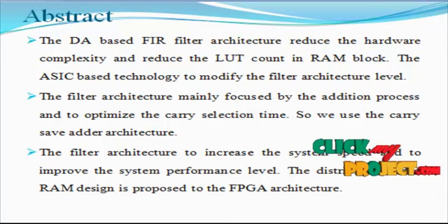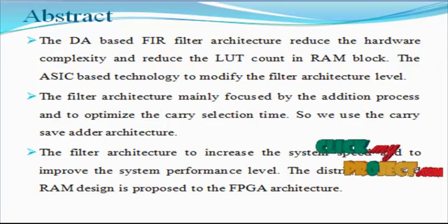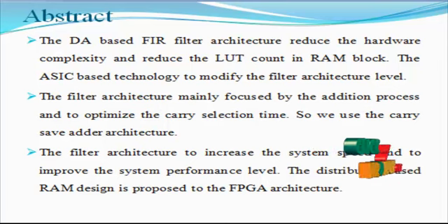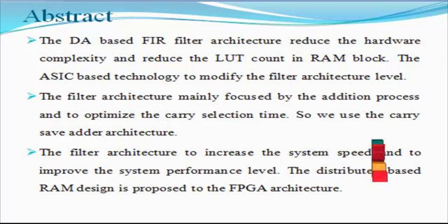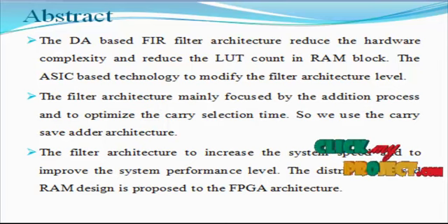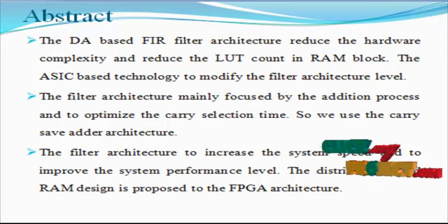Reconfigurable finite impulse response filters, whose filter coefficients dynamically change during runtime, play an important role in software defined radio systems, multi-channel filters and digital up-down converters. However, the well-known multiple constant multiplication based technique, which is widely used for the implementation of FIR filters, cannot be used when the filter coefficients dynamically change. On the other hand, a generally multiplier based structure requires a large chip area, consequently enforcing a limitation on the maximum possible order of the filter that can be realized for high throughput applications.